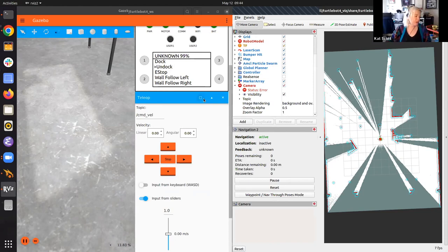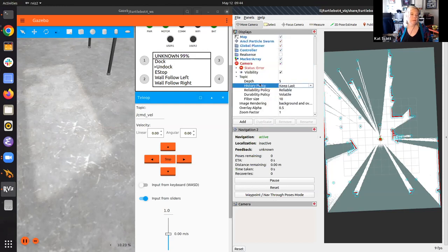This is called the sim-to-real problem in robotics and computer vision. And it's going to vary a lot. If you're just programming the robot to go forward, back, do a motion sort of thing, it will probably be pretty accurate. If you're doing deep learning, recognizing these things, it could be significantly different. It really depends on the fidelity of your simulation and where the fidelity matters, essentially.